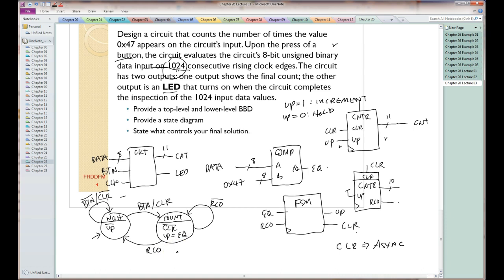Now, last thing here is how this is controlled. So here's control inputs controlled by the state machine. Up input is essentially an internal control, so once again, this is the internal signal. The clear and the ups are coming from the state machine for that circuit controlled, and that is all we have. Now we could have done this as a Moore machine, but it makes less sense because essentially it would cause me to divide this state into two states, which I don't want to do. It kind of clunks up the problem.